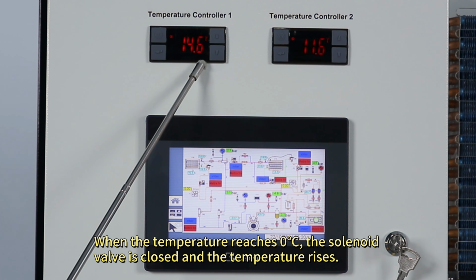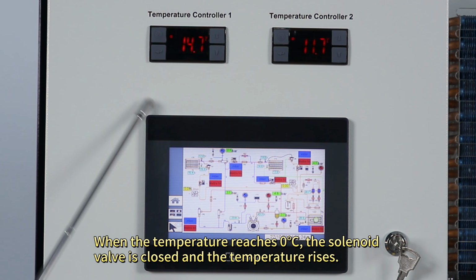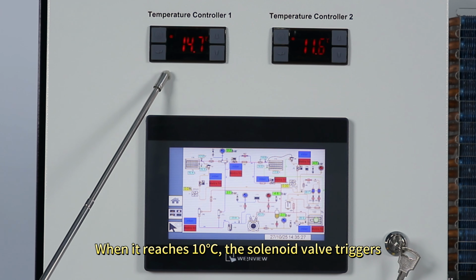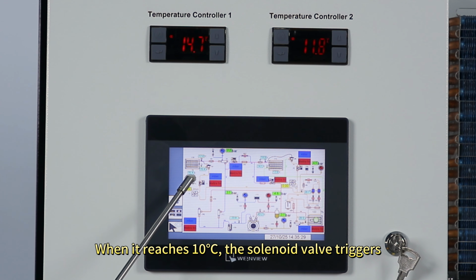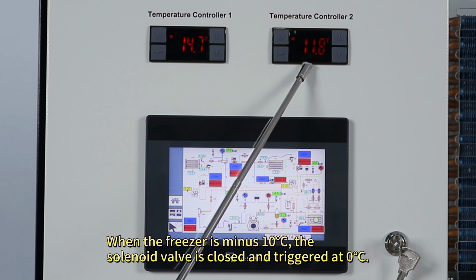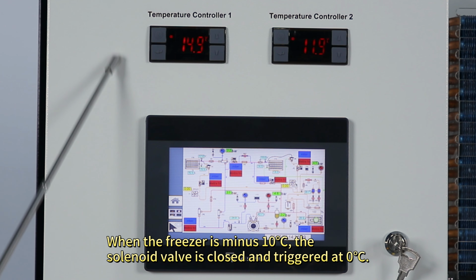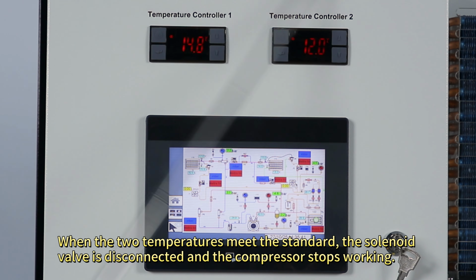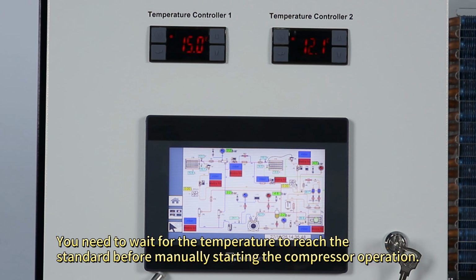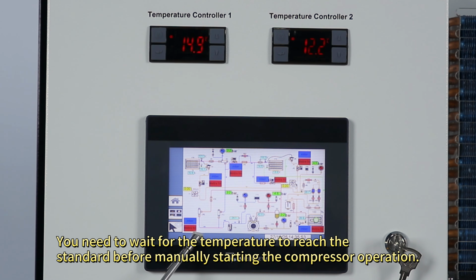When the temperature reaches 0 degrees centigrade, the solenoid valve is closed and the temperature rises. When it reaches 10 degrees centigrade, the solenoid valve triggers. When the freezer is at minus 10 degrees centigrade, the solenoid valve is closed, and it triggers at 0 degrees centigrade. When the two temperatures meet the standard, the solenoid valve is disconnected and the compressor stops working. You need to wait for the temperature to reach the standard before manually starting the compressor operation.